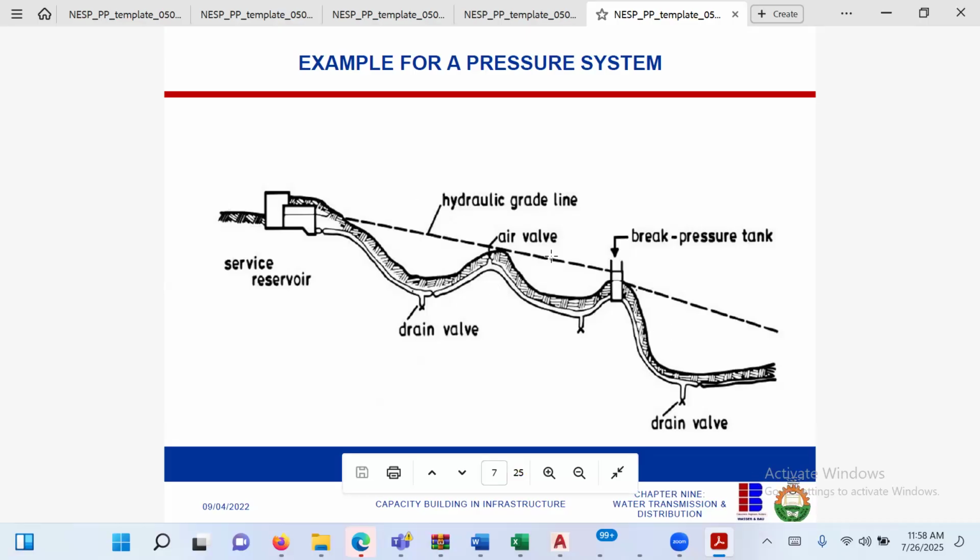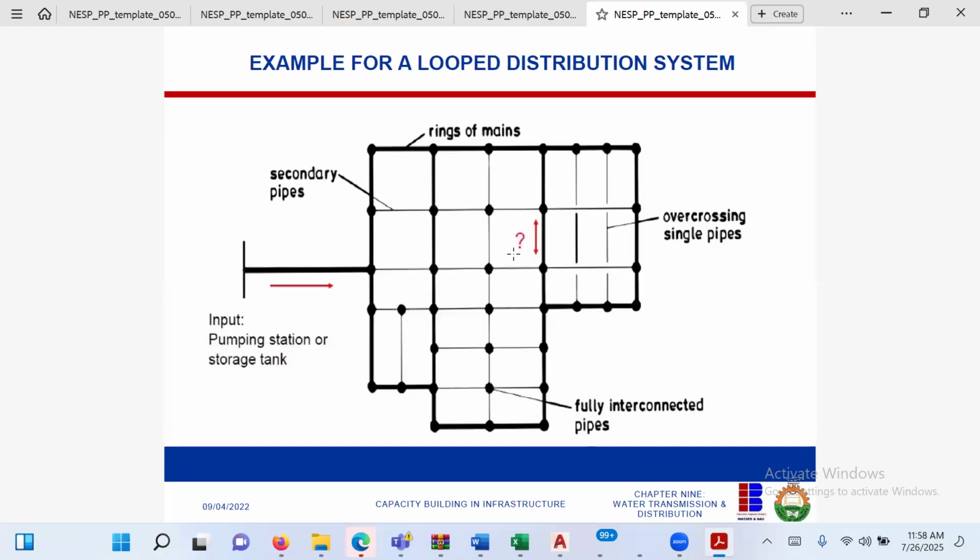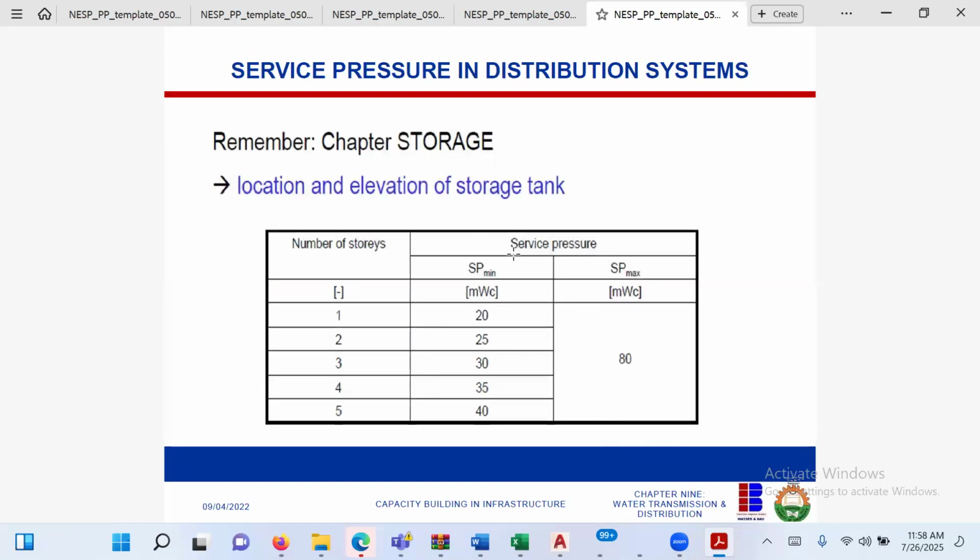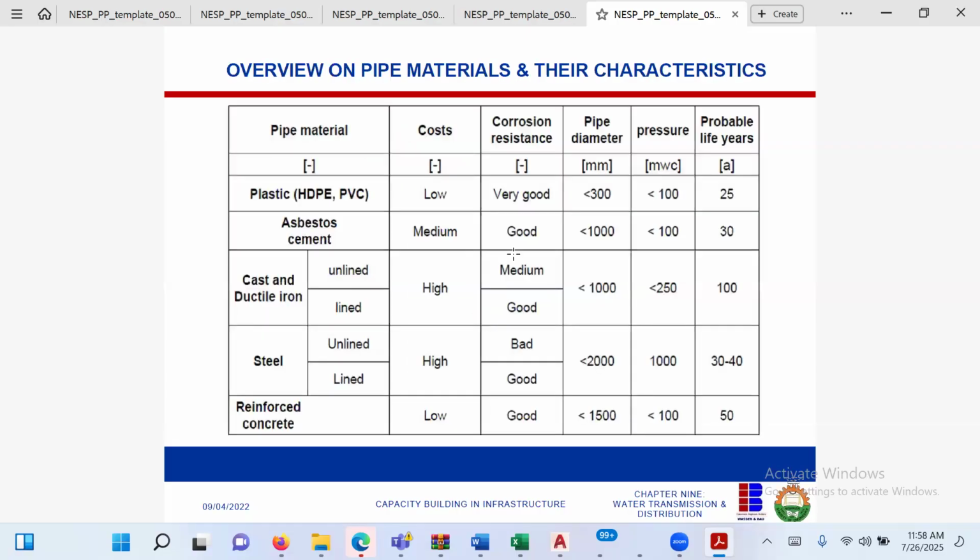So this is giving us the idea of where to provide valves, some pressure release valves, very, very important. Because pressure will build up there. Air pressures will build up there. Bubbles. They need to be released to keep the system safe. So I've explained this before.